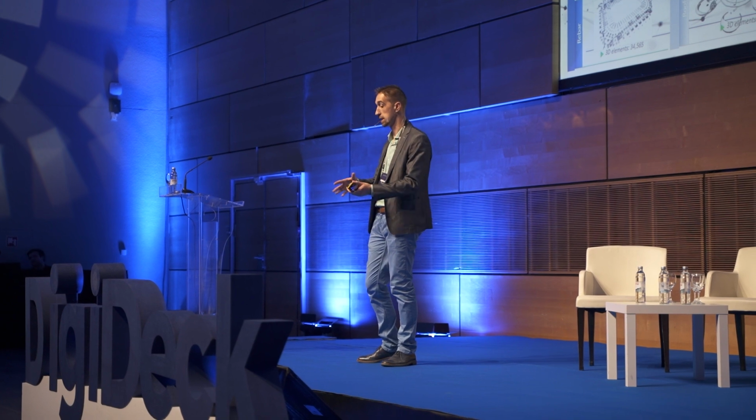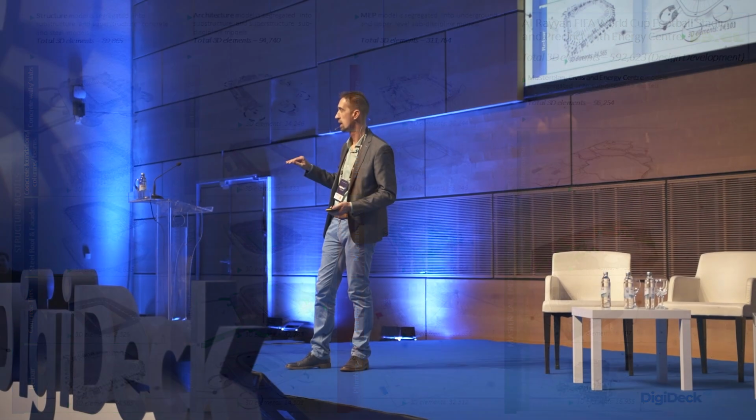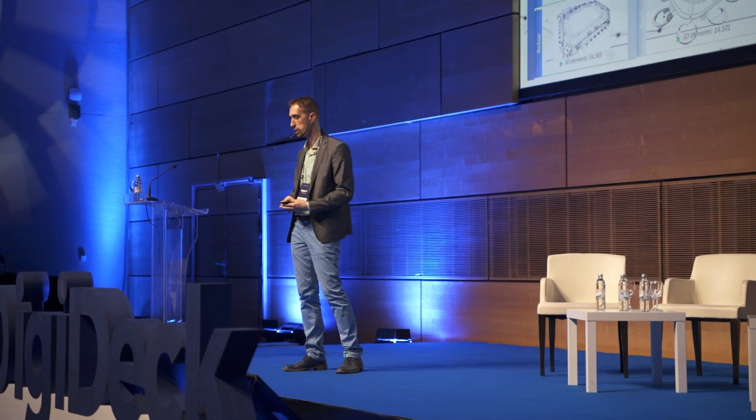An important thing for such a large project is to properly organize BIM files and segregate models so everyone can use them without any issues. We decided to segregate this project into separate models by disciplines, and because of the quite big size of the project, we needed to separate even further. Each model was exported into multiple IFC files based on underground elements and elements above ground, or substructure and superstructure elements.